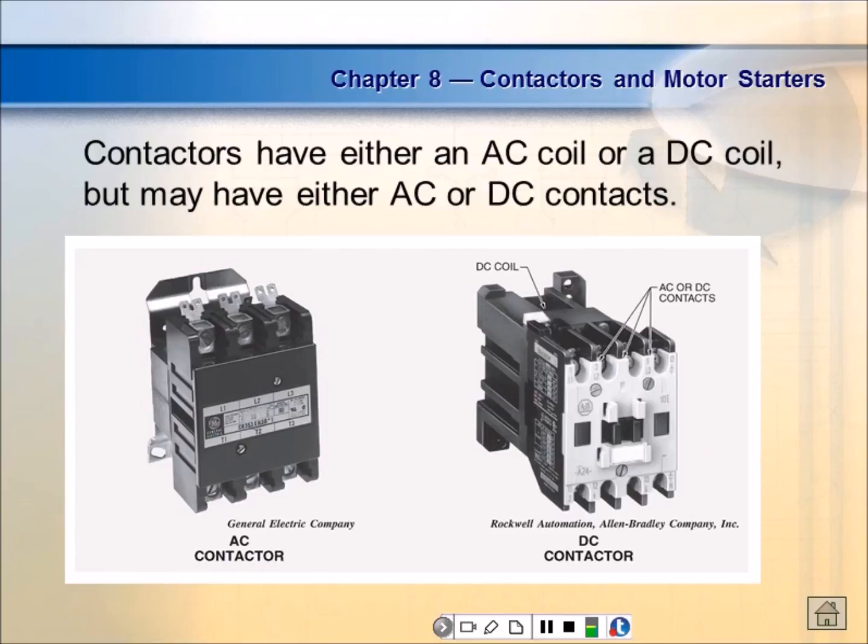Contactors have either AC or DC coils, but may switch either AC or DC contacts. Y'all understand that? So the contacts can control a different type of voltage than the one we use to control the coil. Are you okay there?